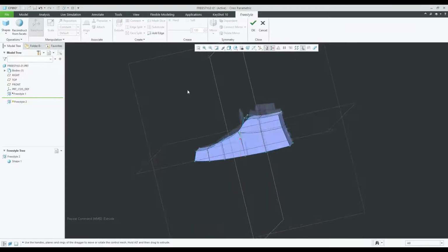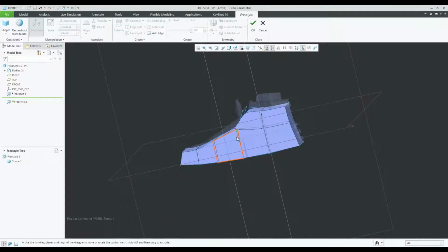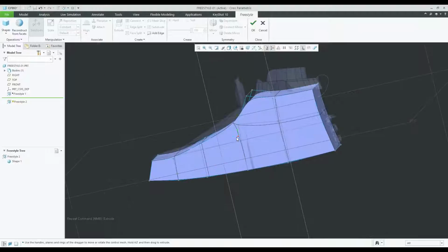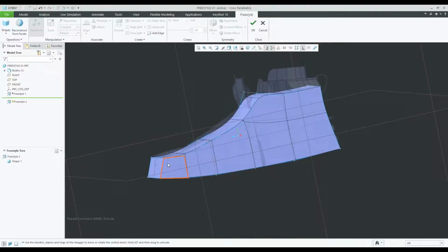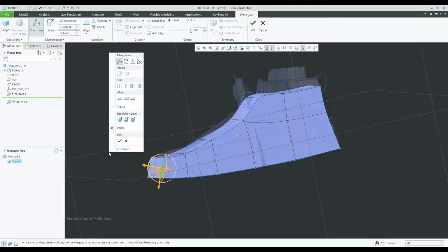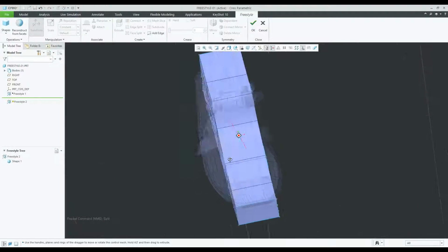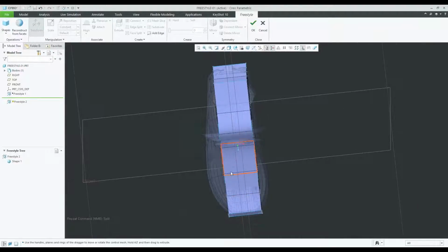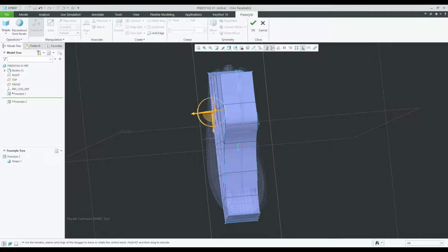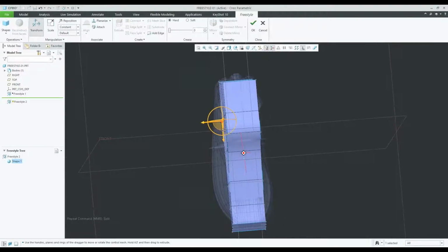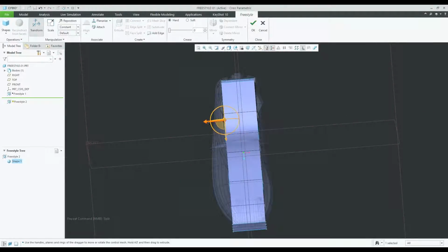I may say that, hey, you know what? I don't really have enough geometry here to develop this model further. So if I want, I can grab this edge, for example, right click, subdivide, and then I have a little bit more to work with, right? So I can say, I need to start to define the shape from this top view. So now I can grab that point down there, for example, and drag that out to here.